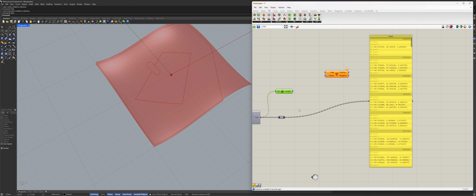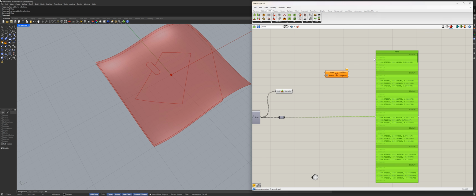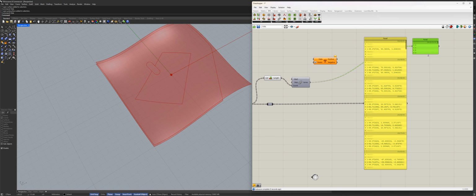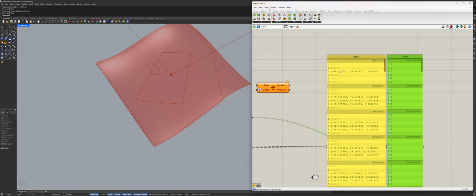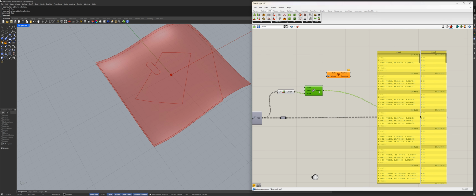What next I want to do? I would like to create the indices. So I basically want a separate data structure which will contain indices for all the elements. Can I do that? Yes. Series. This is the node which you used before. Starts with 0, step with 1, default values, length is 6. Let's check. It will give me the uniform structure with values 0, 1, 2, 3, 4, 5, 0, 1, 2, 3, 4, 5, and so on and so forth, right? So null 0, null 1, numbers of the point 2, and so on and so forth, one by one, okay?